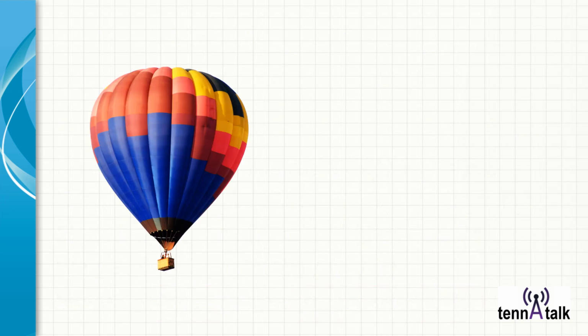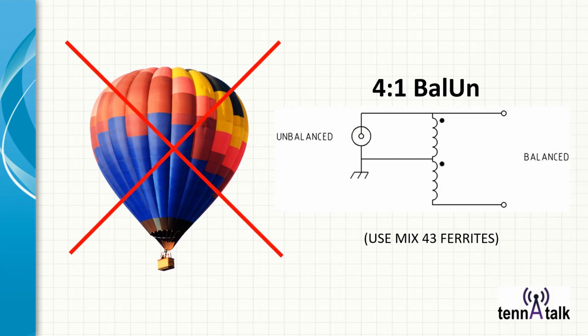So now let's take a look at BalUns, or balloons. No, not balloons. Let's take a look at a BalUn. Here it's a 4 to 1 BalUn. And I know it's a BalUn because the input ground is not directly connected to either side of the output. It's somewhere in the middle. And so that immediately tells me it's a balun. I have balanced output versus an unbalanced input. Coax is unbalanced. And BalUns and Ununs, in other words, TLTs, typically use mix 43. Sometimes you'll see other mixes, people are experimenting with them, but for the most part, most people have most experience with a mix 43.